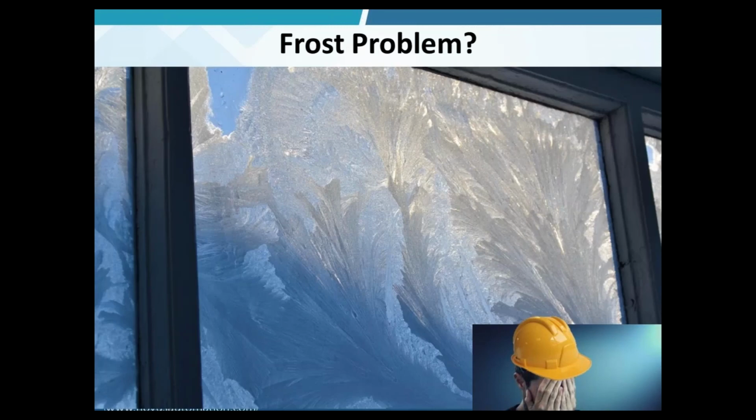The freeze drying process works by freezing the material, then reducing the pressure and adding heat to allow the frozen water in the material to sublimate. Frost is one undesirable problem in freeze drying processes and can cause collapse or irreversible eutectic melt, or the process may not meet the required crystalline structure of the material.